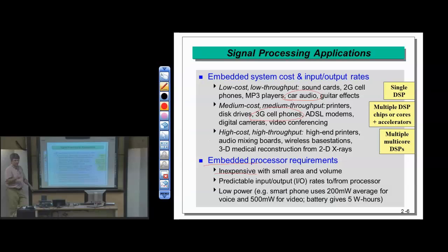The CPU itself takes 11 cycles to service an interrupt, and that's it. It's predictable. Now, if there's an operating system on there, there may be additional latency, but the CPU itself, 11 cycles, exactly. It's not random. So as you move blocks of data on and off the chip, you know what it will take to service the interrupt for that data transfer.